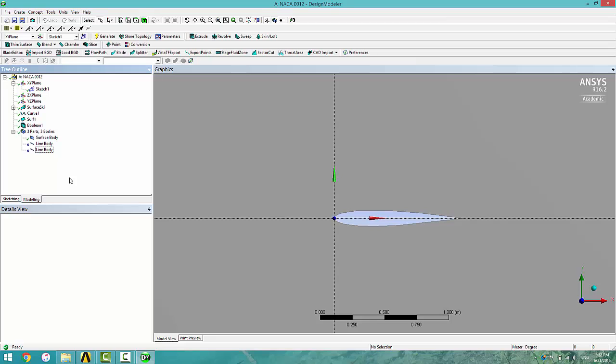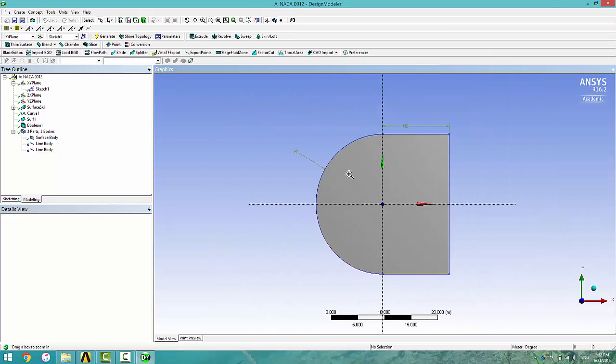The last thing we should do here is to create the name selections to use in Fluent. So I'm going to zoom out. I'm going to select the Add Selection feature. Hold down the Control key button. Click the curved edge on both horizontal edges.